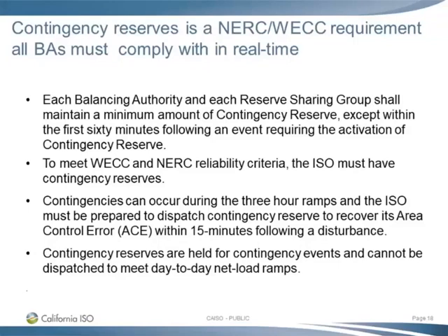And the reason why you have that 5-minute addition is, sometimes you may not know exactly when you have a contingency, so to give the operator some time to react. In the old days, they threw in that 5 minutes to bring the recovery time to 15 minutes. But the spin non-spin requirement is really a 10-minute product.